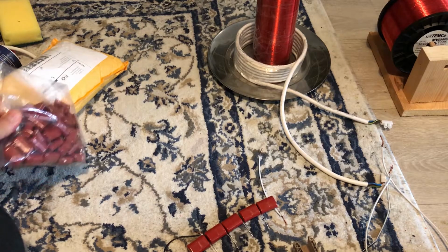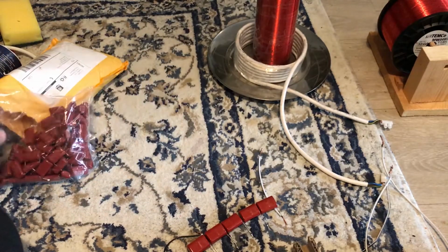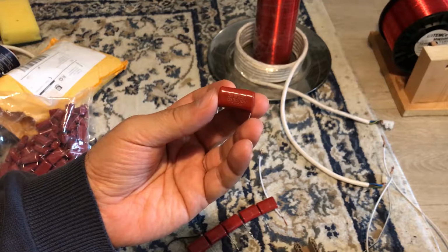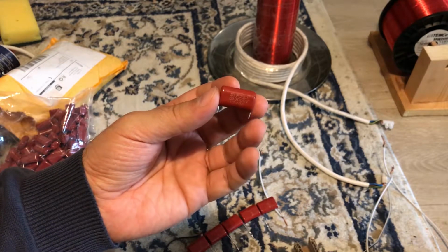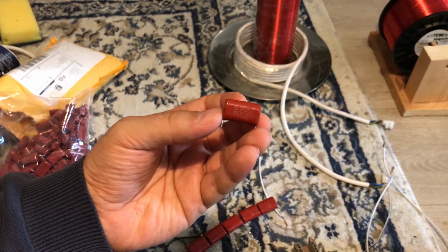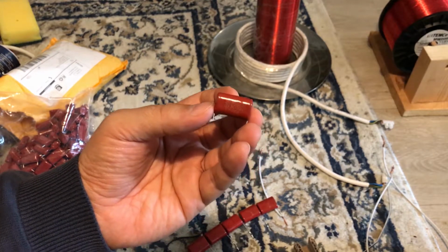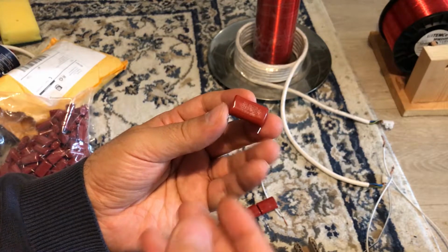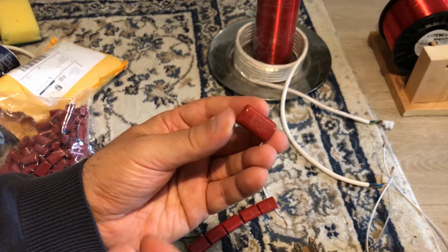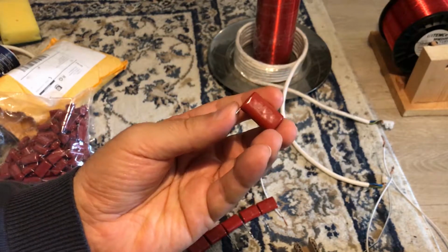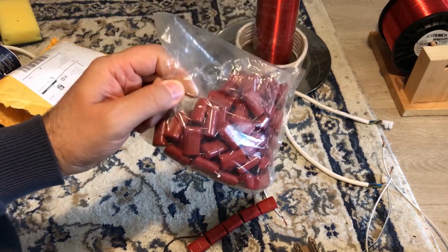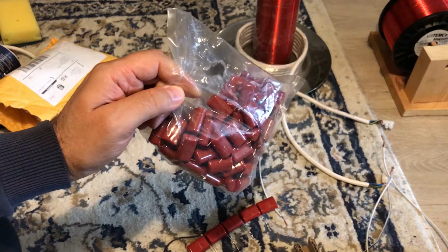Another type of capacitor is this type. These are also red capacitors, but they have a slightly different structure. These are rated at 3000 volts and they are 8.2 nanofarad. These capacitors are really well made and they can actually handle even more than 3000 volts, so maybe 5 kilovolts. Of course, if you apply higher voltage than what is written here, you're going to shorten the lifetime, but for a quick test you can overstress them to maybe 5, even 6 kilovolts. But these capacitors are also more expensive, so for 100 of them you have to pay approximately 50 euro on AliExpress.